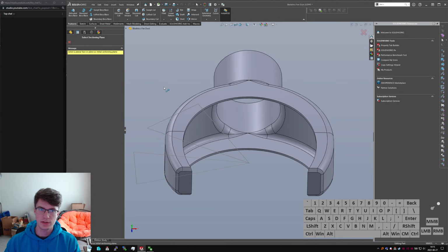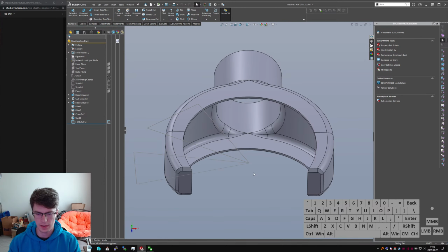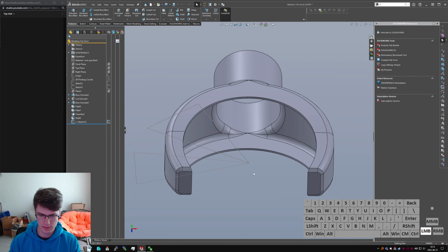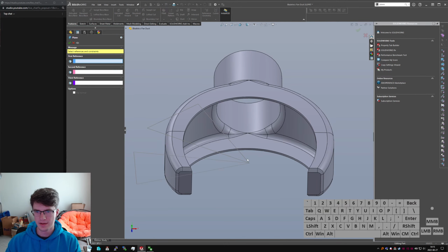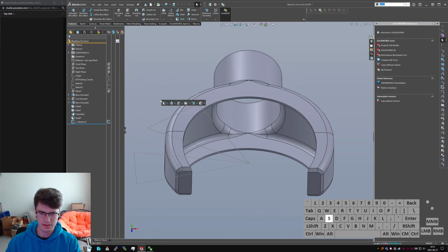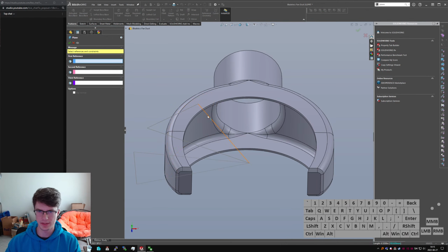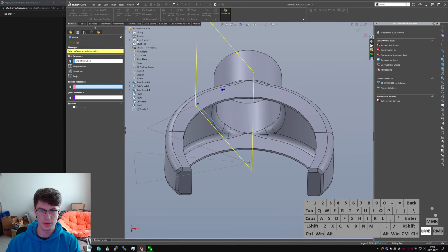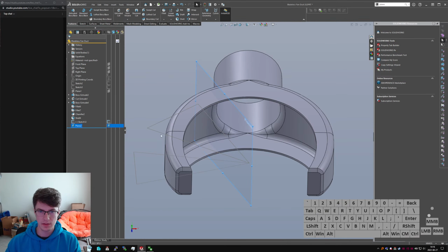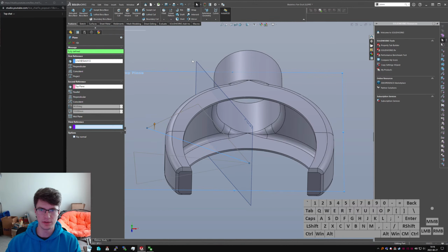Then we'll do some live section planes. Ah, dang it. How do I make... I want a plane, if I could spell plane. With that... Oh hey, it's even in the right spot. Input is incomplete? What? Oh. It probably wants some other plane to be perpendicular too. Top plane, please be perpendicular, sounds good. If I pick these both at the same time and say make a plane, will it do it? It will.